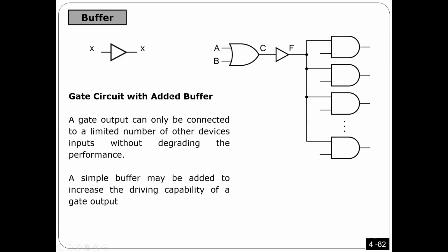Anyway. So the next thing I want to explain now is something we call a buffer. You should understand what a buffer means. We have a very simple problem, and the buffer is going to help us solve the problem. So let's first explain the problem, and then I'm going to tell you how the buffer is going to solve it. In many electronic situations, I want to connect a circuit to another circuit.